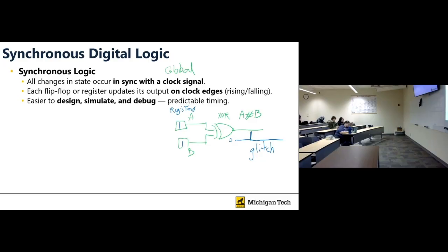Like a spike or hazard. This spike happens in practice, in the lab. But on paper, that's okay. The formula is exactly correct. Like you say, F is A bar B plus A B bar. That's the formula. Math says that's fine, but in reality, you see this. So, oh, what? The math says this, but because of this problem, this is something you can see in practice.